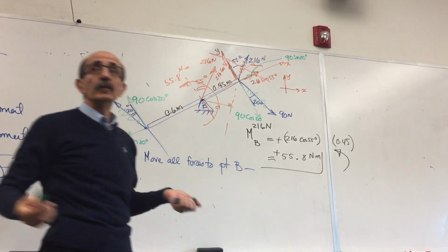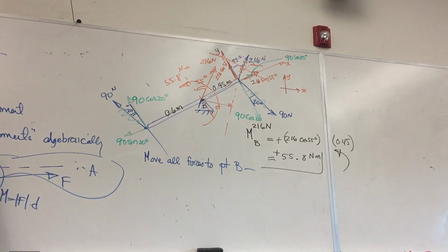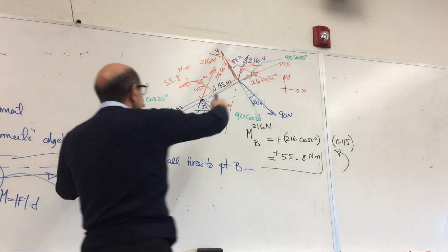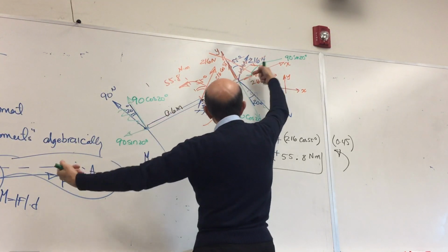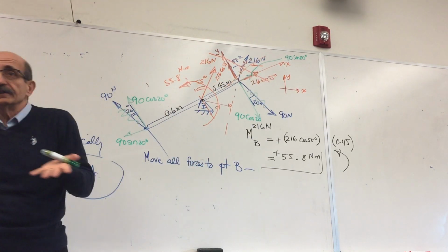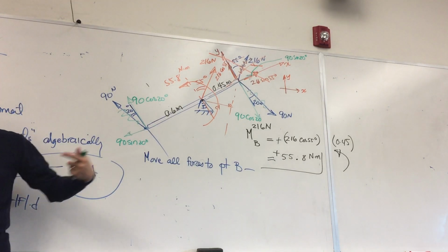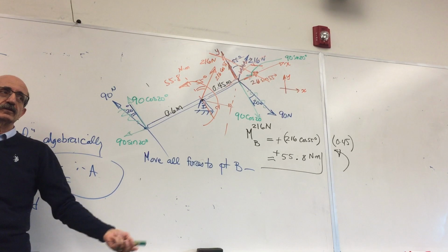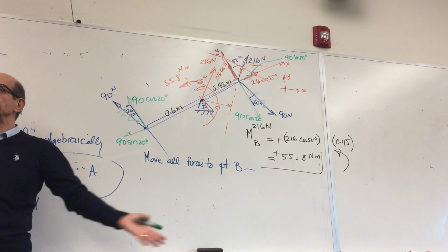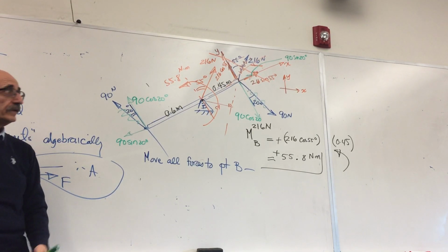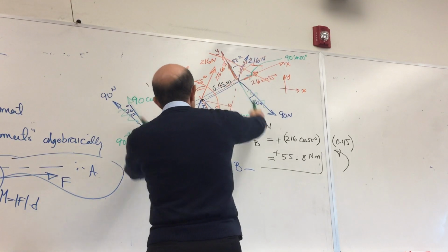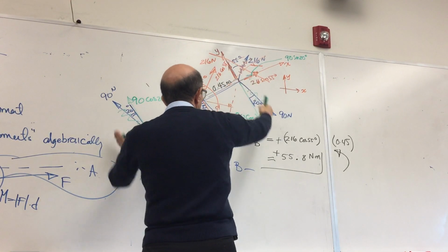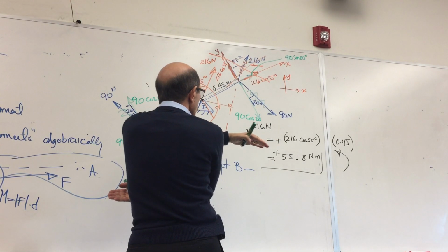I need to find the moment of each of these components. These two obviously are a couple, but it happens that they're both acting along the same line. So they cancel each other. They don't generate any moment, they don't represent any force, right? It's only the couple resulting from these two which is going to act clockwise.